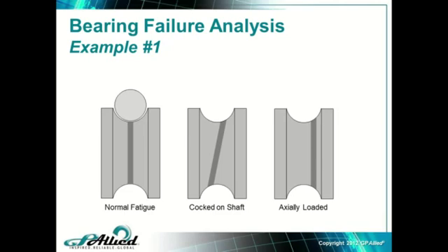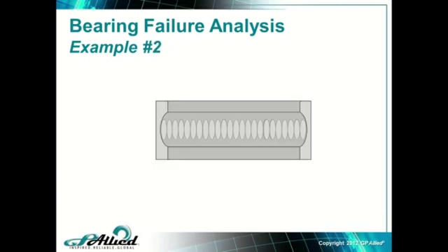And that is where we can start to make some big step changes in the performance of our equipment. Another example. You guys may have seen this. Now, I had to draw this in PowerPoint, so these ovals are a little bit bigger than they normally are. But this wasn't just through the load zone. This was all the way around the outer race, just continuously, and all the way around the inner race, continuously.